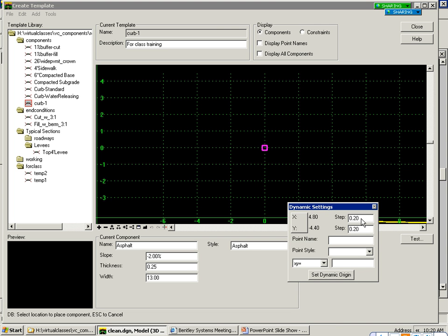A step, if I make that a 1, we'll tab that in 1. What happens, notice when this jumps, it jumps in series of 1. You see that? So it's jumping on the grid in series of 1. Let's make it a little bigger even. We'll go 2 and 2. So see, it has to go a long ways to make the jumps. Let me slide one more time. It can only jump by increments of 2. 2 being the master unit.